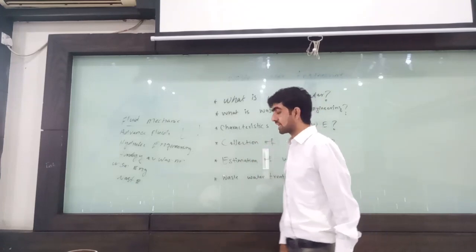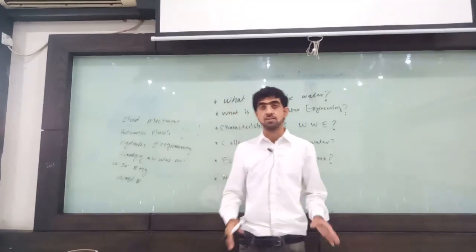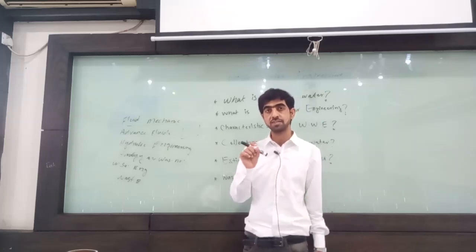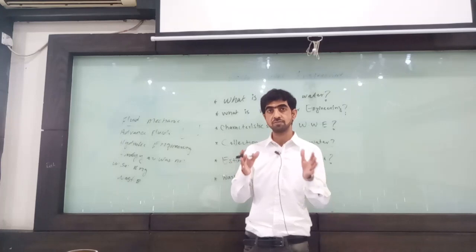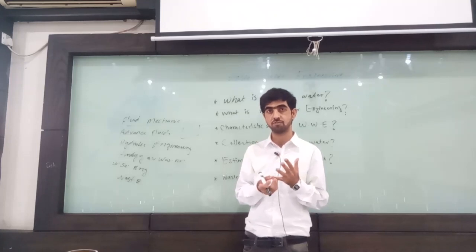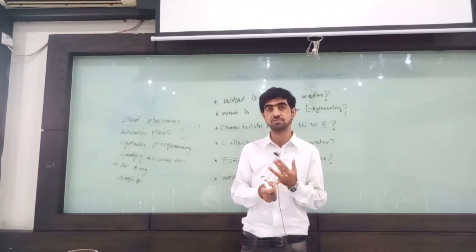Okay. So the collection of wastewater I have already explained, covering different areas. First of all, we estimate that 80% of drinking water becomes wastewater, so we can consider 80% as wastewater. That is one technique.